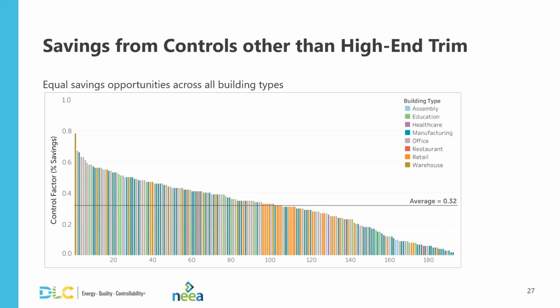So buildings with high savings are likely the result of a combination of, say, implementing multiple control strategies, aggressive control settings, such as shorter occupancy shut-off time delay, or maybe beneficial site characteristics, for example, ample and deep penetration of daylight, and maybe occupancy and space usage patterns and user behaviors.